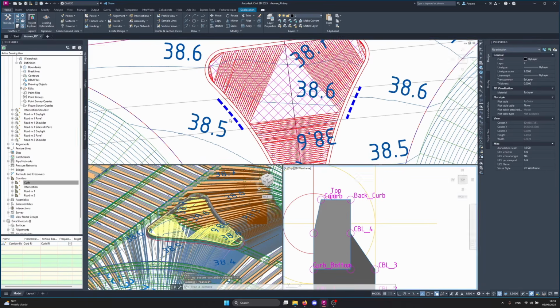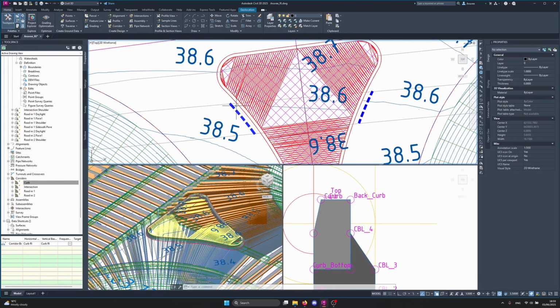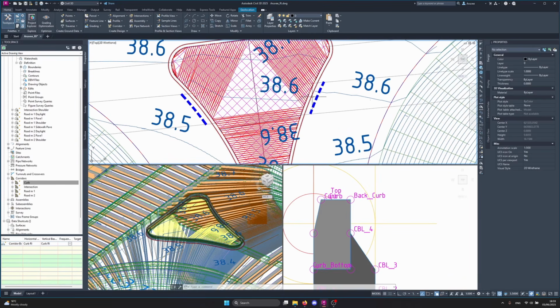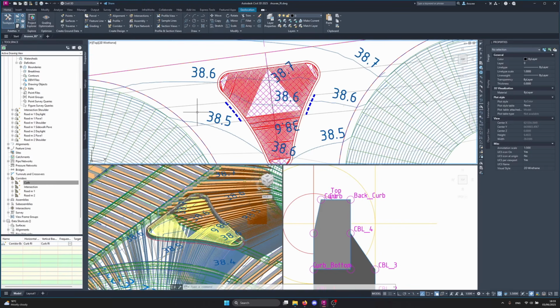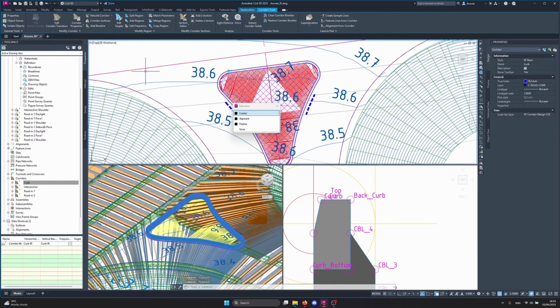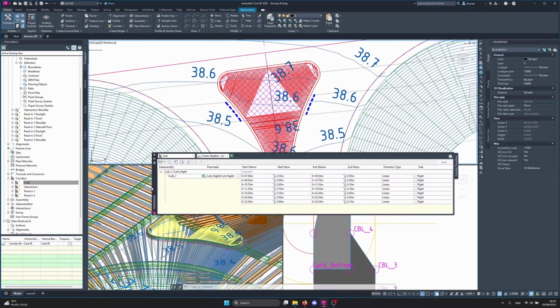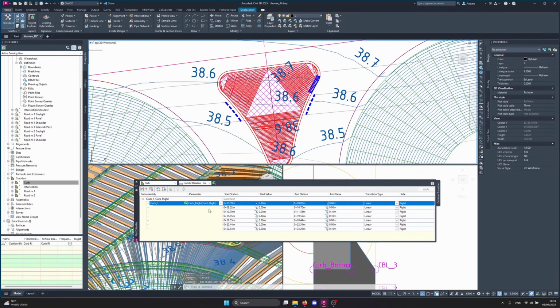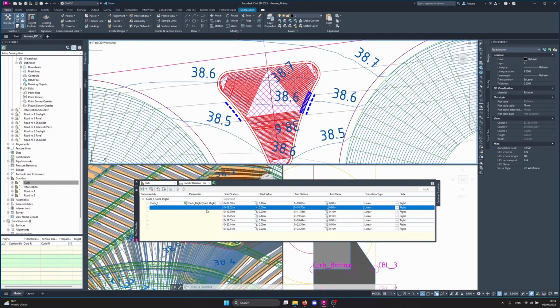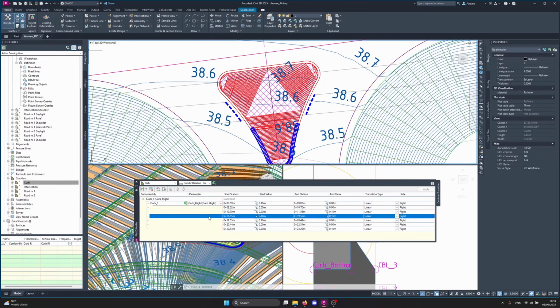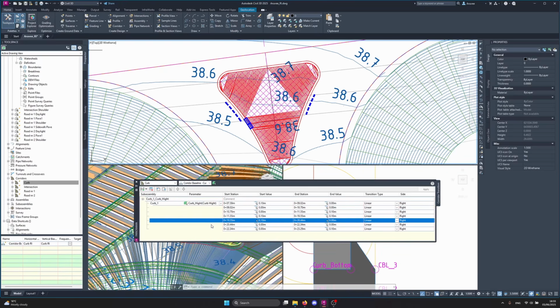For example, this blue dotted line is showcasing that the curb right here should be 0, and here as well, so the pedestrian could walk, right? And with the corridor transition tool, you can actually make the transition with the curb height. So as you can see, I have regions, 10 centimeters, 0, 0, then again going 0, right?